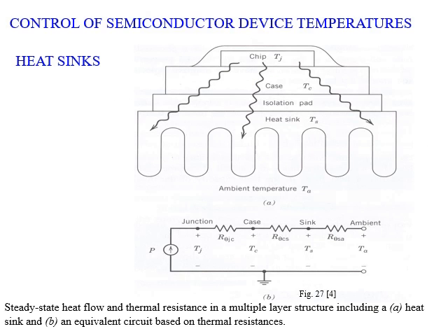Another problem that could happen to our converter is thermal problems, and we need to protect against it. This comes from the fact that our switches, the transistor or thyristor, have limited thermal capacity. Its thermal capacity is low. On the junction at the back of the thyristor or transistor, you find a metal, which is the junction here. It cannot handle heat. If heat increases, it may burn and we lose it.